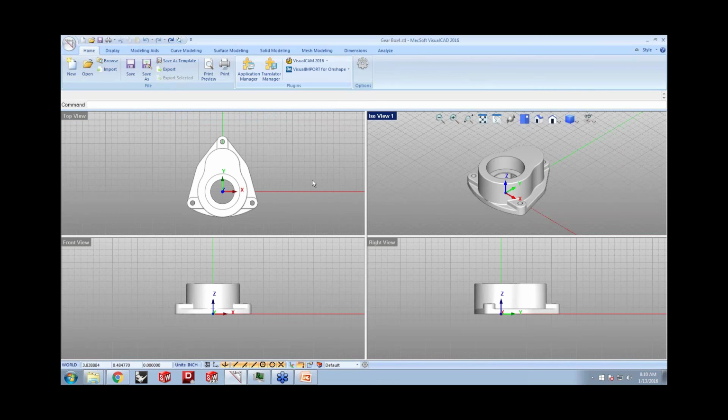Now I'm going to go over the different milling CAM modules in here. So I'm going to click the Visual CAM menu. And first, I'll go through our free mill module, which is a free 3-axis milling solution. Before I select the free mill module, I'll just prep the part. I want to add a little base to this. So I go up to the solid modeling, and I can say I want to create a box in here. And I'll just throw in a box at the floor of the part, and I'll put in a height, give it a thickness of 1/4 inch.